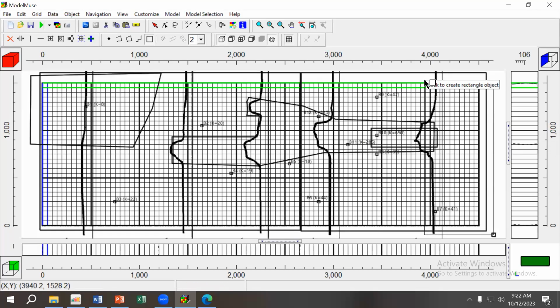So again, how to know these things? This just comes by your best judgment and using your common sense. If you don't have good judgment and you don't have experience in these things, your model will not calibrate and you will not get good results. Somebody will tell you, because you're not connecting your high hydraulic conductivity fields, you're losing this connection between your main channel in the aquifer and the river, for example. So they will tell you to connect these.